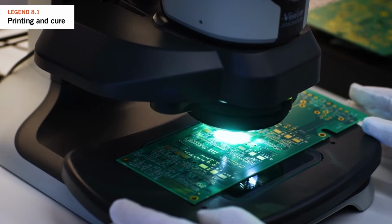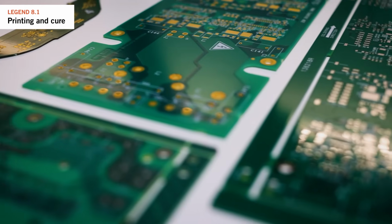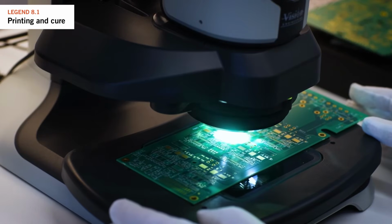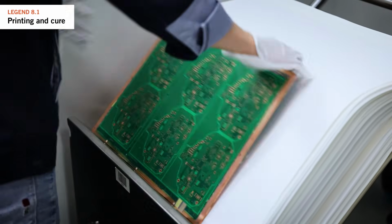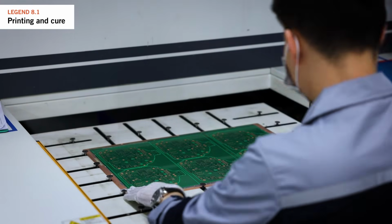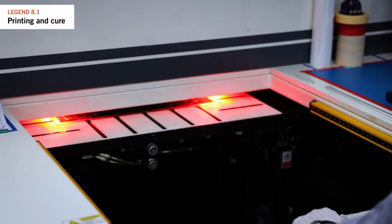We mark the PCBs to include component identification, factory marking, part numbers, and date code or batch references for traceability. All marking except the component identification can also be added using negative Soldermask. In some of the factories we use inkjet technology for direct legend printing. Like other processes, precise registration is crucial to avoid printing on exposed copper features.